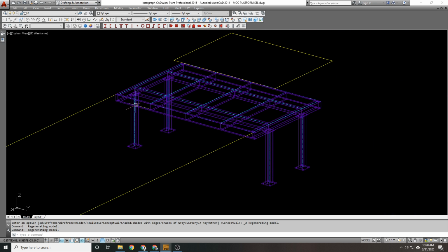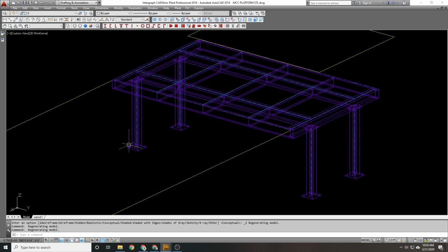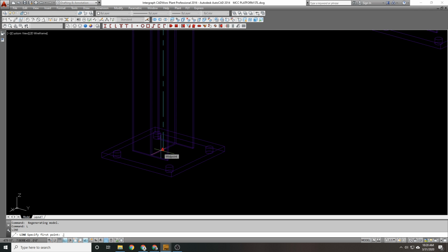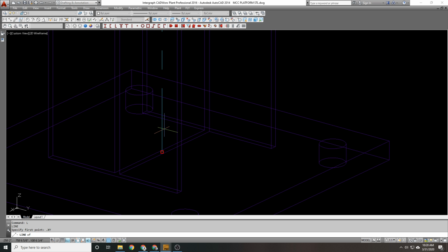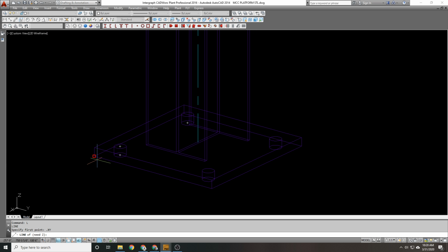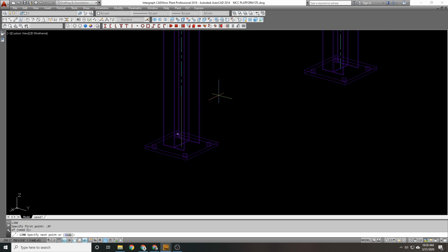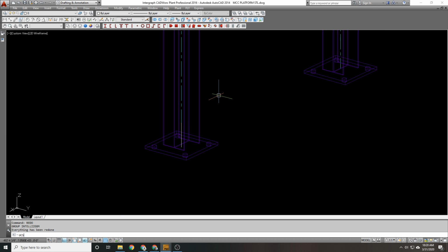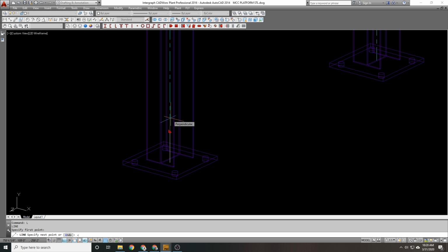So seeing as how nobody needs to get underneath here, we can take the brace all the way to the ground. So company standard for us is to always go 6 inches from the ground. So I'm going to do a dot XY of here. But I want to start down here with my Z. So I'm going to come up 6 inches. Okay, I'm going to say UCS right. From here, I can say less than 45.